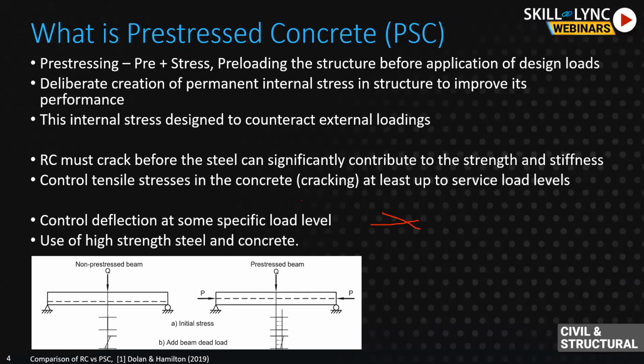Whereas timber, the compressive strength is not as high as concrete, but at least timber is a bit versatile. It can take both compression and tension. That's why sometimes it comes really handy. Whereas concrete is very terrible in tension. So wherever there is tension in our structural design, we definitely need something that will eliminate tension. And that's the whole concept of reinforced concrete, adding reinforcement wherever we expect tension.